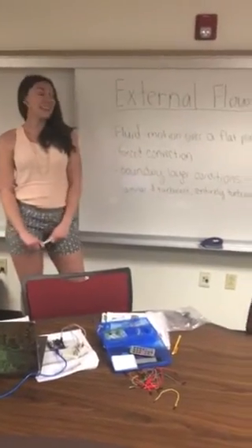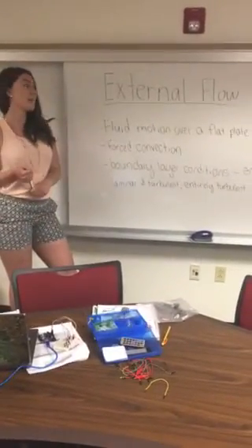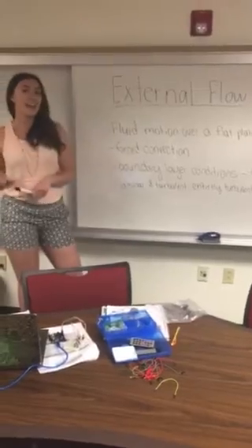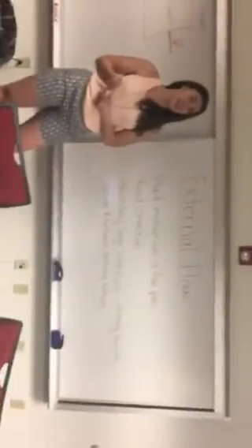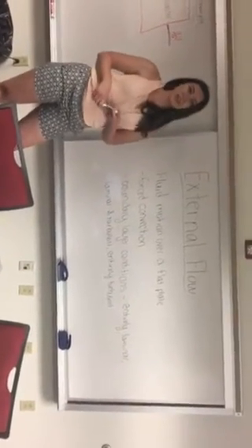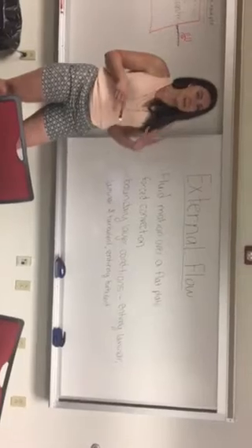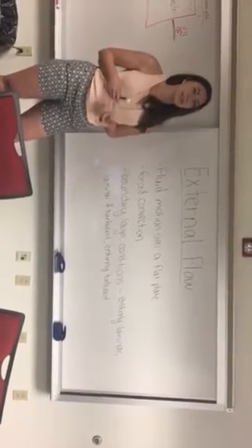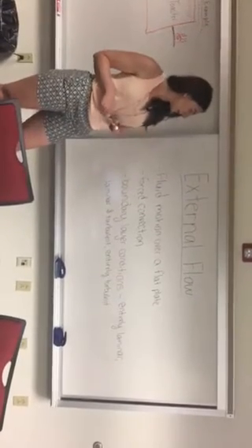Hi, I'm Megan Ruth, and the heat transfer topic that we are going to be talking about is external flow. External flow is the fluid motion over a flat plate to either heat it or cool it. The main topic for external flow is forced convection, which uses either a fan or a pump to blow fluids such as air, water, or oil over your flat plate.